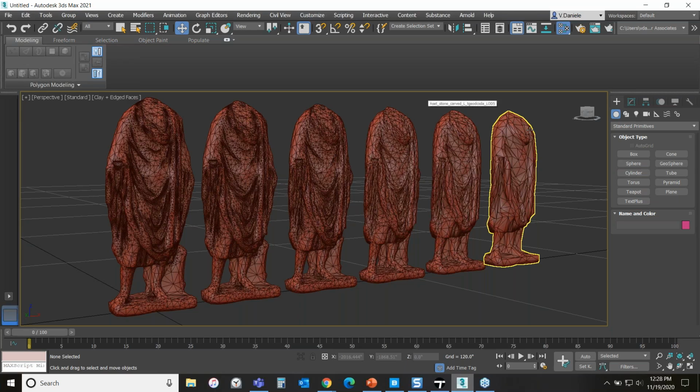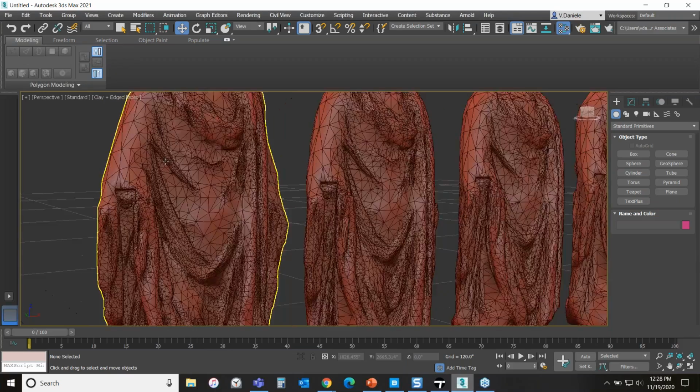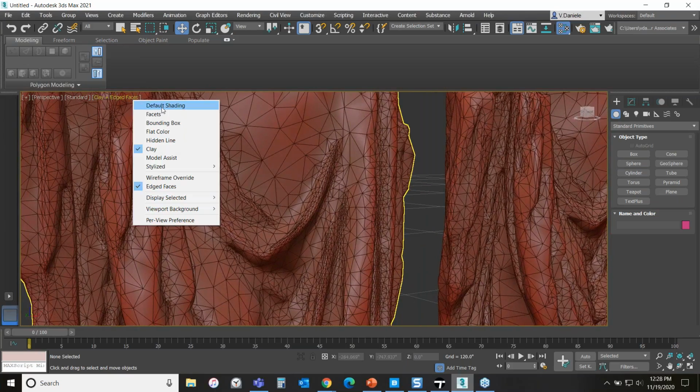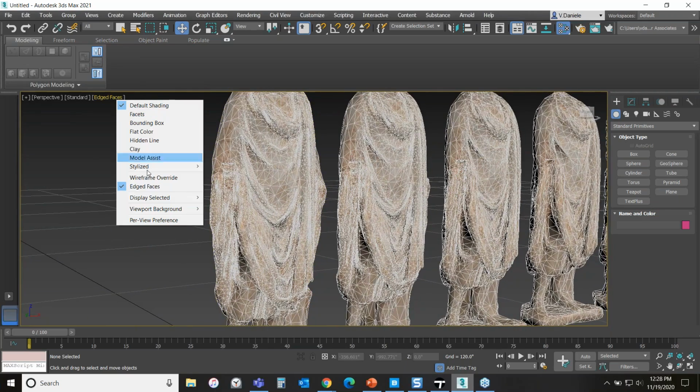We're basically grabbing a real mesh, creating a 3D object from it. I just like to show this because it shows you what the mesh looks like from that LOD 0 all the way up to your 5. But then also, because of the way that photogrammetry works, we're not just capturing surface detail, we're actually capturing the image detail on that surface and creating a really robust, nice texture map and material ultimately that we can assign. So I'll just switch this over right now. If I zoom up on this, yeah, the mesh looks really nice. It's pretty dense in the folds of the statue. As soon as I actually turn on the material, let me turn off the wireframe override here.